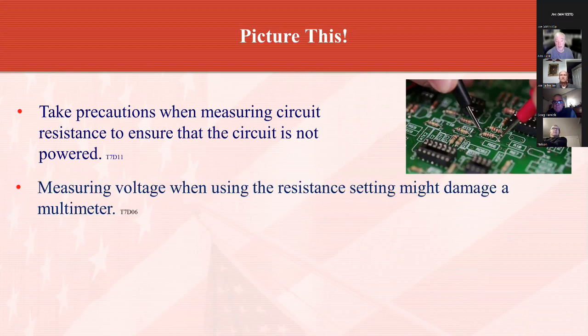You may get false readings, but other times, if you're working around really high voltage electrical units, like a tube radio or a more antiquated radio, although the oldies are the goodies, you can end up laying on the floor, maybe forever. So you really want to make sure that when you're working on equipment, it's not powered, whether it's a low voltage or a high voltage situation.